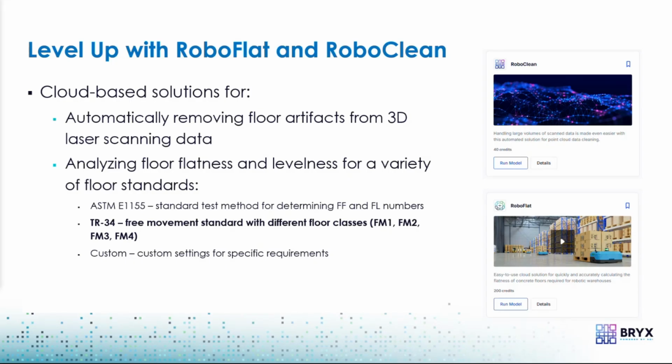RoboFlat supports a variety of floor standards, ASTM, TR34, and also custom standards. So as James had mentioned, for those clients that have specific requirements, you can specify custom settings using RoboFlat and test the floor according to those specifications.